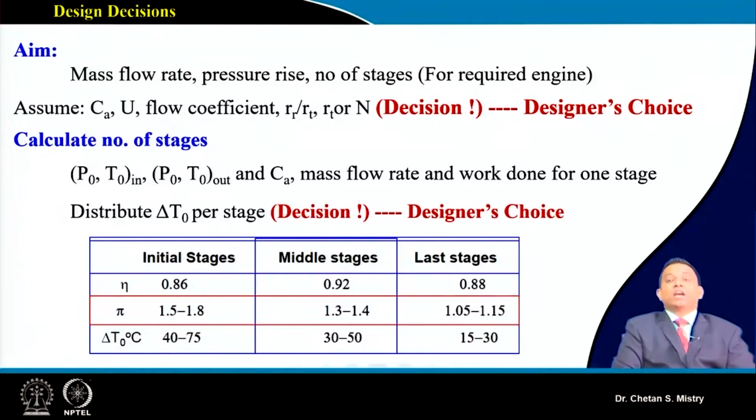When we discuss the later or rear stages of our axial flow compressor, the blades have lower height because of the compressibility effect. Because of the rise of pressure, the change of density brings a change in area, and that is why those rear blades are shorter.